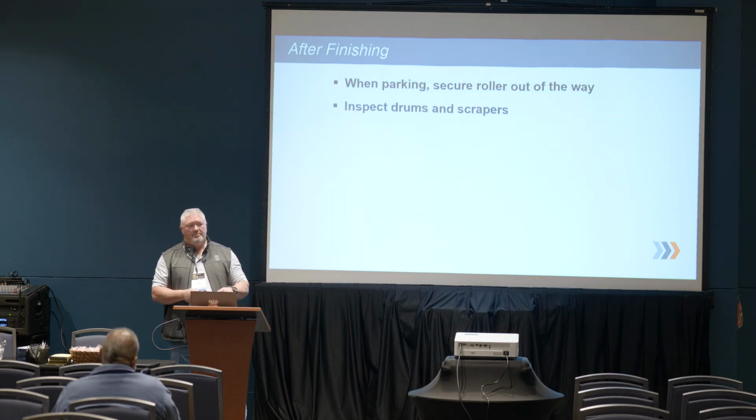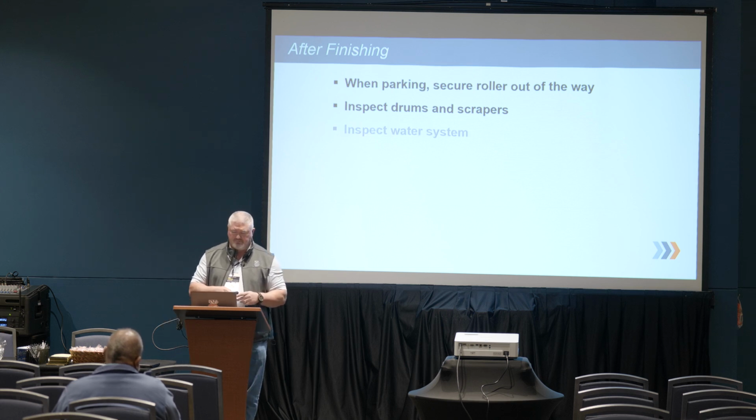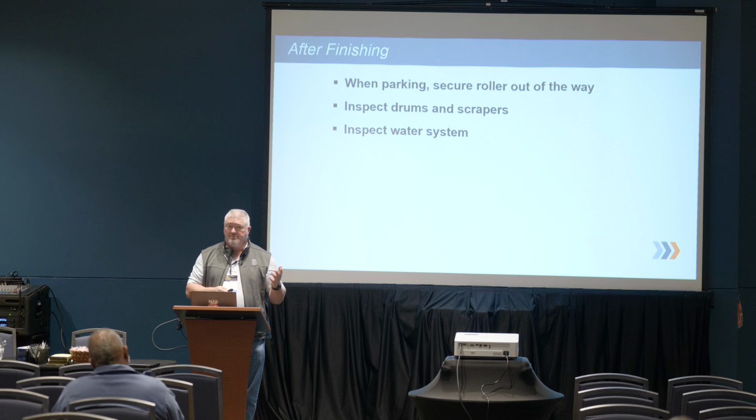Inspect the drums and scrapers. Spray the springs down with WD-40. Make sure they're off the drums if you're going to be traveling down the road. Inspect the water system, clean the filters.